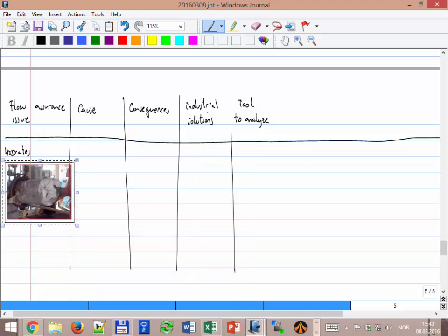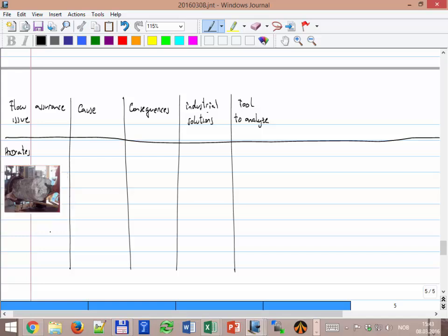Okay, what causes hydrates? We said that it happens because the molecules of water arrange in some kind of solid pattern. It's kind of a box where the light hydrocarbon molecules want to go inside and keep it stable. So, what do you need to form hydrates?